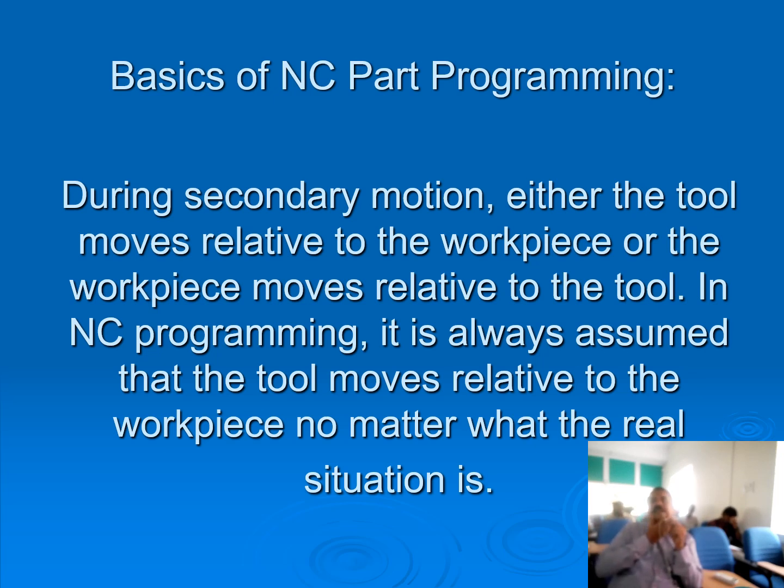Now the basics of NC part programming. During machining, either the tool moves relative to the workpiece or the workpiece moves relative to the tool. In NC programming, it is always assumed that the tool moves relative to the workpiece no matter what the real situation is. So here is an important point to be noted. When it comes to programming, we make sure that the tool moves relative to the workpiece, no matter what the real situation. In a real situation, the workpiece may move relative to the tool, but in programs we assume the tool moves relative to the workpiece.